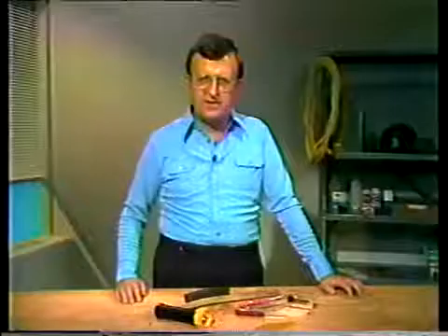Now, welds in a moisture separator or drum can also be affected by erosion, corrosion, and cracking. Erosion and corrosion can attack the weld metal just like they attack the metal in the rest of the vessel. Cracks are likely to start at or near the welds.